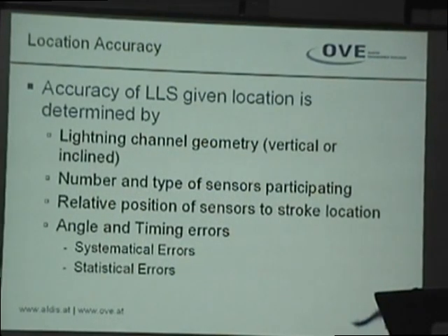Yeah, then there's also the time interval. A time interval of 500 milliseconds between strokes should be on the safe side, the default configuration. I'm still using 500. But we increased the maximum flash duration from 1 second to, I think, 2 seconds, because we've seen flashes more than 1 second long.